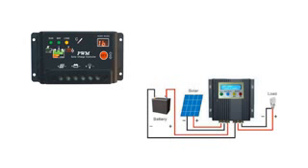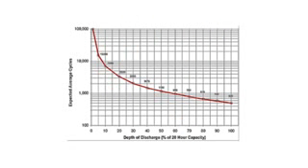And a charge controller is there to protect the battery from exactly that. The battery shouldn't be drained completely. If it is drained fully, then the number of charge cycles the battery can be used for gets reduced. A charge controller gives you control on protecting the battery.